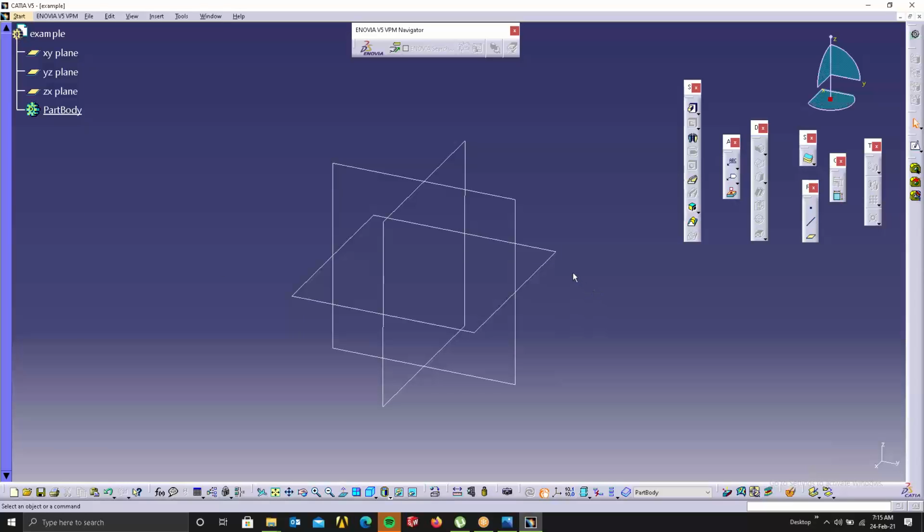So you have to think like that, from the modification point of view. That's why I'm very specific. You should think about the modification point of view, and whatever you're doing should be very simple. One more example is fillets. If you're doing a sketch, this person will apply all the fillets in the sketch itself, exit it, and pattern it.